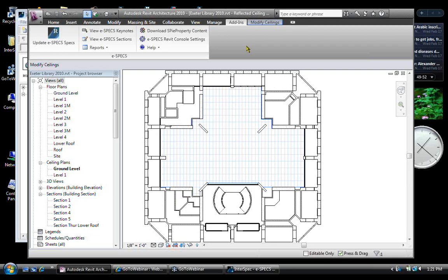Gil, can we stop there for just a minute? When you say the Omniclass code, you mean using an additional classification, like for the products? Yeah, a perfect example would be a window in a project. I might establish that window in Uniformat as a wood window. If I looked at Omniclass, that classification for that window might appear in several locations. It might appear in double hung windows, it might be appropriate in casement windows, and it also might have wood windows and aluminum windows established in the materials portion of Omniclass.